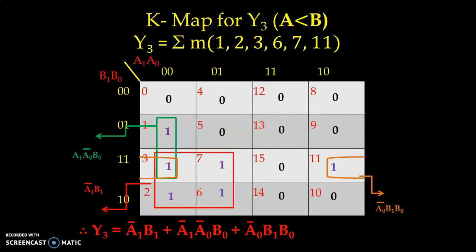We can verify that y1 and y3 both are complement to each other, and for y2 we have 4 different product terms and none of the variables is eliminated. So we will have to simplify further for y2, and then we can implement our logic circuit.